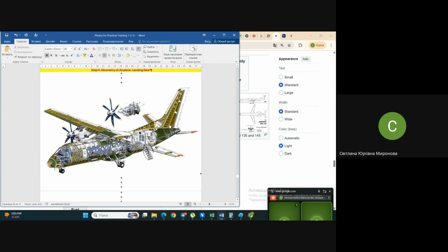Somewhere there was a nacelle between flaps in order to hide landing gear there. I don't think that you need to invent some divertive schemes of landing gear hiding, or rather retracting. For this very first approximation, if I were you, I would hide the landing gear main legs into the fuselage under the bottom, and the nose leg quite clearly under the cockpit.